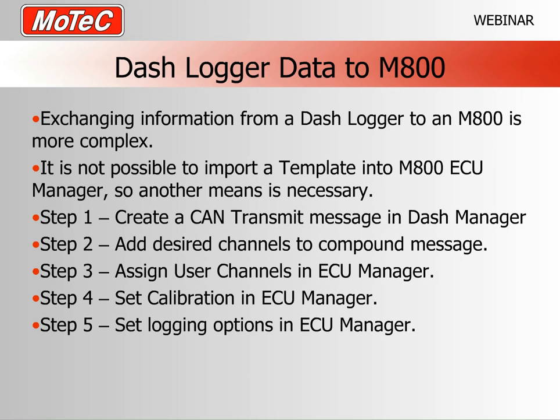The converse is somewhat more messy. Getting data from a Dash logger back into an M800 is another thing that has been set up to make it as easy as possible, but a little bit more detail needs to be gone into due to the nature of how the M800 works. It's not possible to create a template in the Dash Manager which can be imported into an M800, so we have to more or less manually set some of this information in the M800.